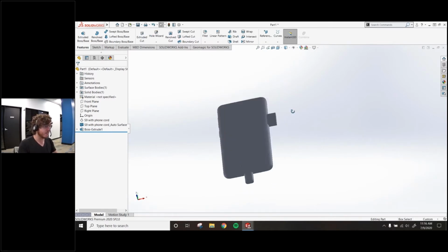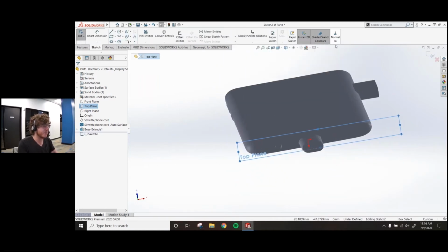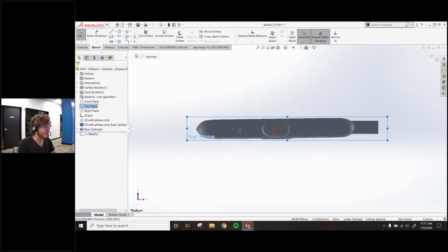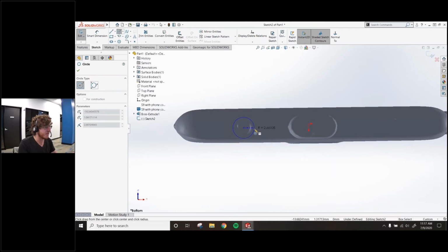So I can go through and find the other locations on this. Again, I've already aligned this to a global origin inside of my meshing software. We could do this inside of the add-in as well, but it's oftentimes best to manipulate the mesh inside of mesh software if you have that capability, which I did. So I did all the alignments inside of Artec Studio.